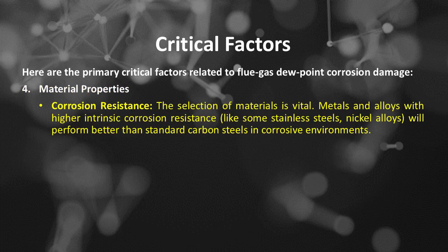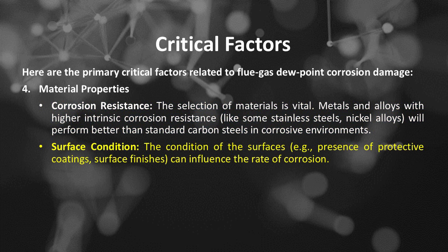Corrosion resistance, the selection of materials is vital. Metals and alloys with higher intrinsic corrosion resistance, like some stainless steels and nickel alloys, will perform better than standard carbon steels in corrosive environments. Surface condition, the condition of the surfaces, such as presence of protective coatings and surface finishes, can influence the rate of corrosion.